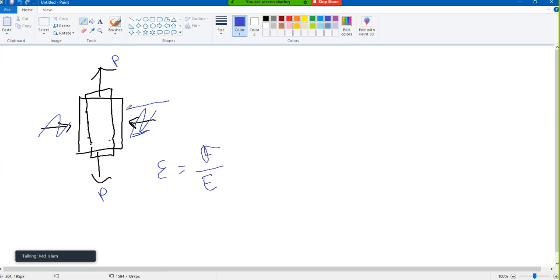But if we push laterally at the same time, that means somebody else is helping me. So then you can see this portion is tension and this portion is compression. So the equation is like, if it is multi-dimensional, then we can write it this way. Say sigma x. Our equation was epsilon x equals sigma x divided by E. Now, other question, should I write Ex? It depends. The most common term is called isotropic.